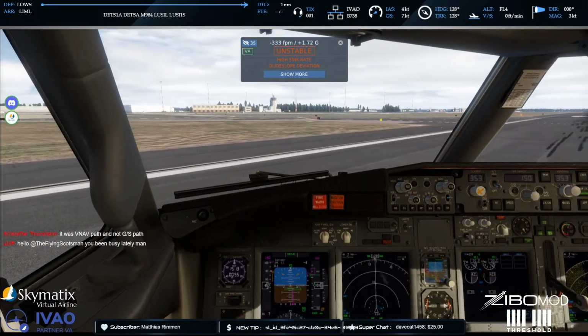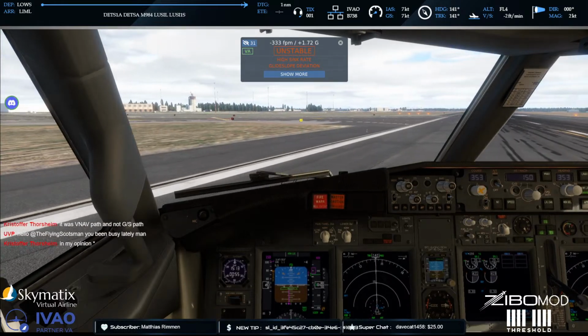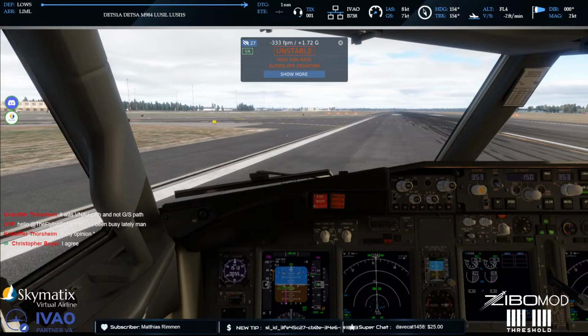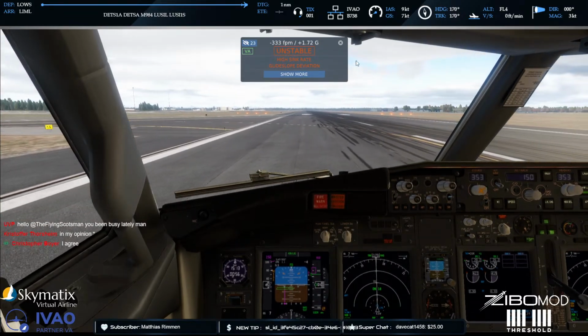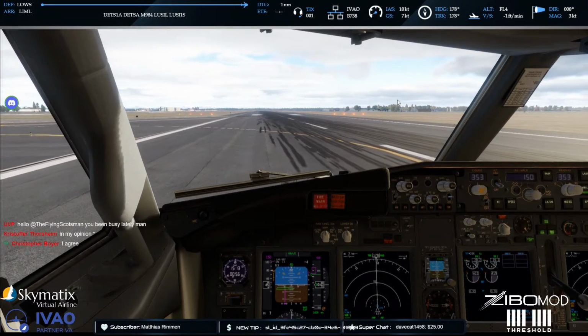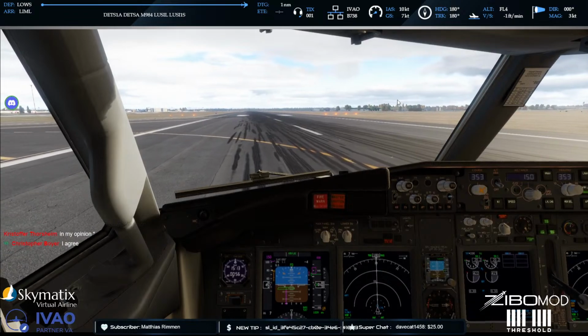Because if you load the ILS approach, with the glide and everything, it should be the mirror of the glide slope. Yes, it should be. So you should have the glide slope, and behind it, you basically have the VNAV path.